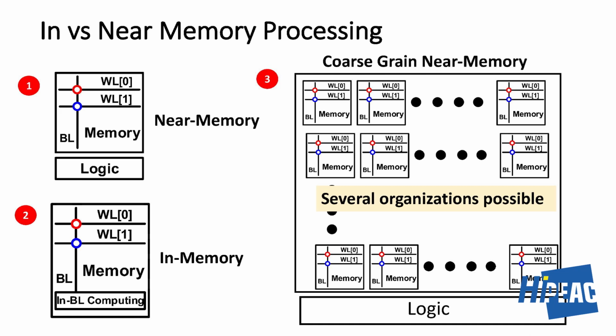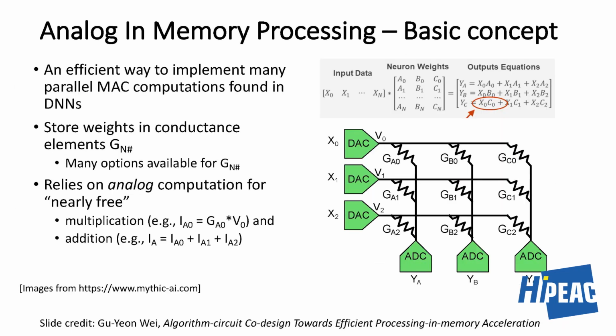Yeah, analog is, let's see, I do have a slide here, it's coming up. There's a flavor of in-memory computing with memristive memories, where you can think of each memory bit cell as a resistive cell, and using Kirchhoff's law, you can do analog dot products. This example is showing that. I'll jump back to that slide for the whole class, but I just wanted to show you this also.